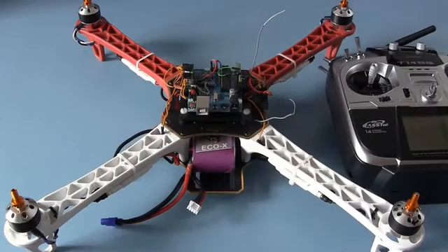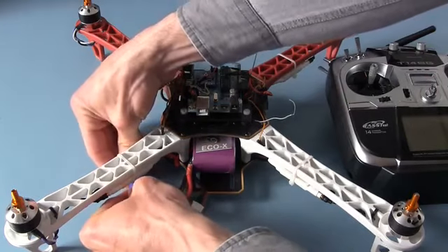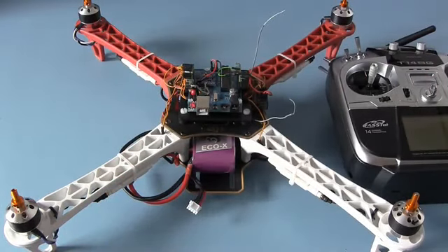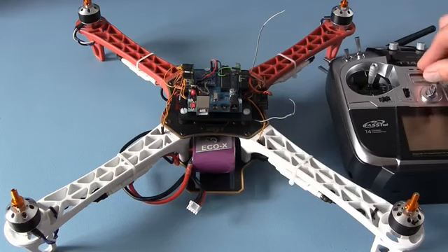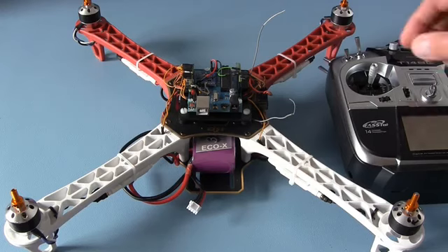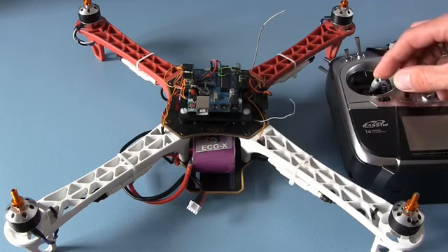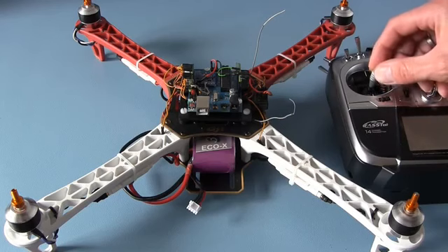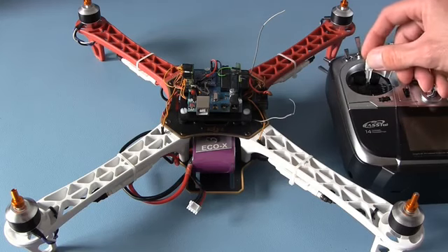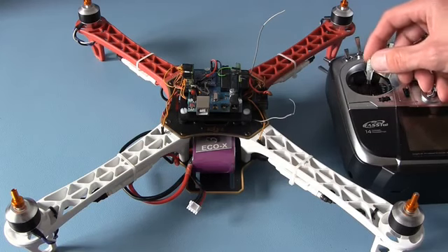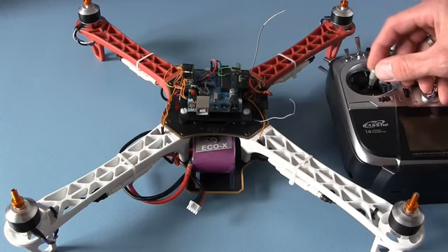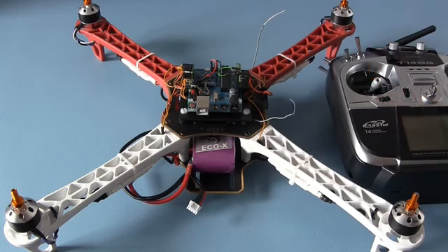Now I've uploaded the program to the quad and removed the props for safety. Turn the power on and we'll see that the red LED is flashing. Now it keeps flashing until the throttle stick is in the lowest position. After that, it is possible to control the motors with the throttle stick. If you set up the transmitter as described in part 2 of this video session, you have a 1000 to 2000 microsecond output pulse, making this program ideal for programming the ESCs when needed.